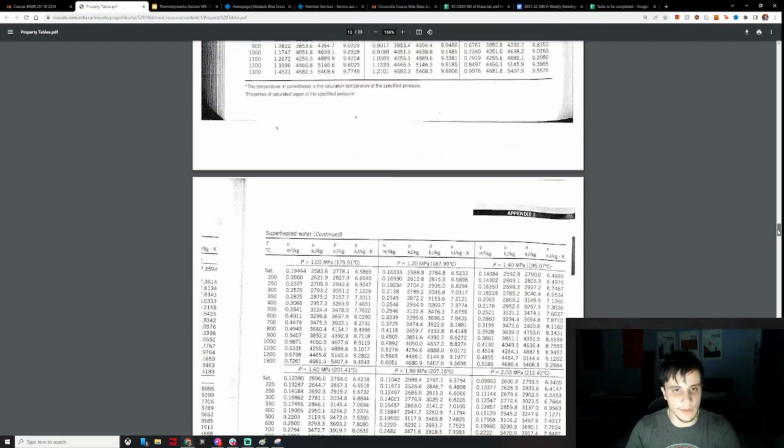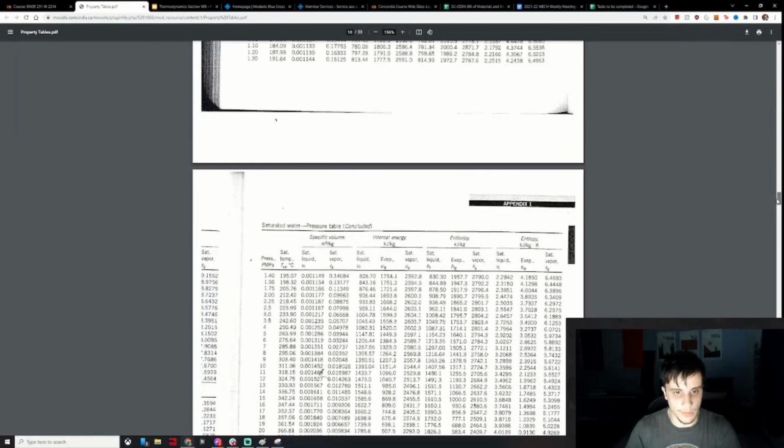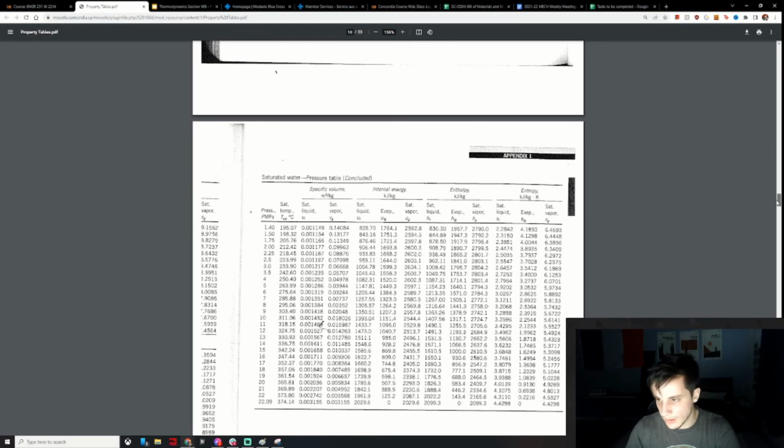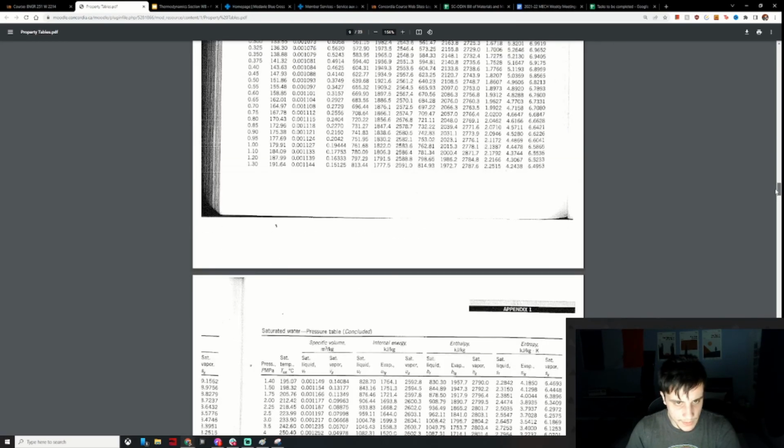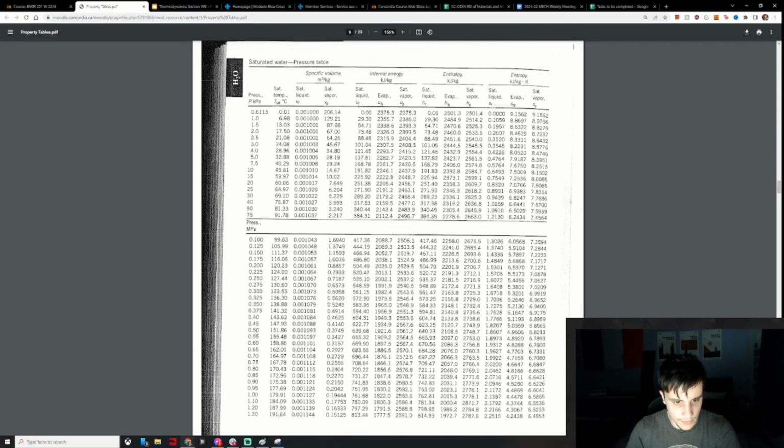Then onto the second state of the saturated vapor. So we're going to go into our mixture water tables, and pressure of 0.5 megapascal this time. So right there. And then go all the way to our saturated vapor specific enthalpy, which is 2,748.7 kilojoules per kilogram. And then finally, for the third and last state of 10 kilopascals, right here, it has a quality of 0.88, so we're going to have to calculate the specific enthalpy between the specific enthalpy of the saturated liquid and saturated vapor.